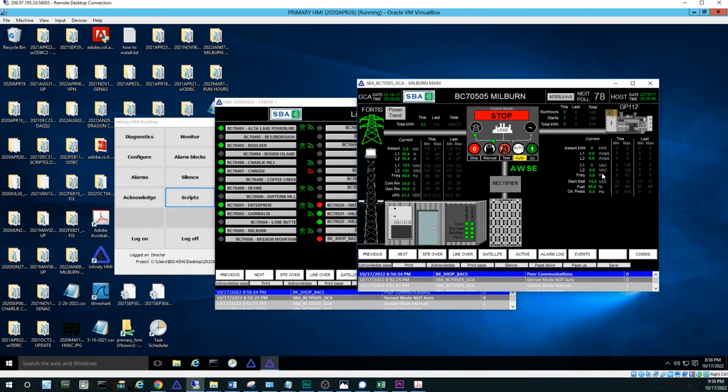The values will take a few seconds to update, as the regular polls come in while the generator is cooling off. It is important not to issue the commands too quickly, or you can easily lose track of which ones are queued, which can cause undesired operation. Before moving on to other tasks, it is recommended to wait for the active mode indicator to update to auto. This will ensure that the generator is standing by to start in the event abnormal utility line power is detected.